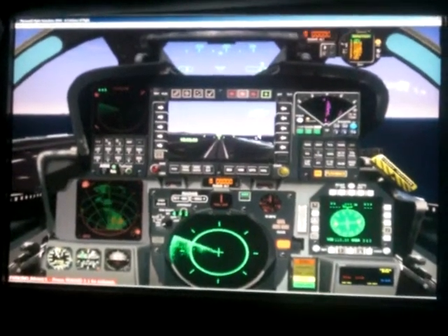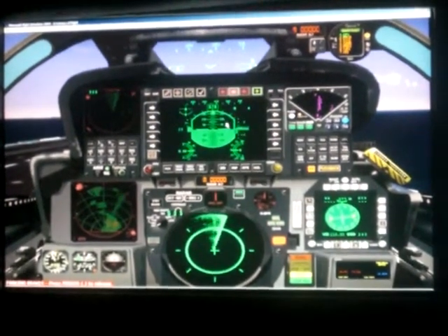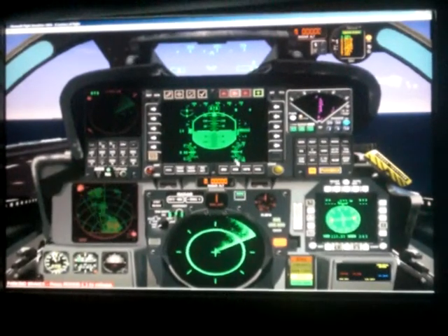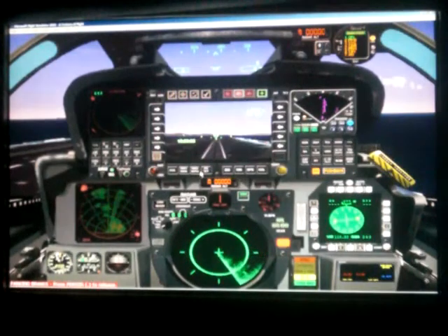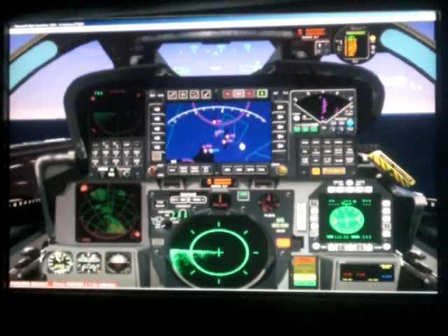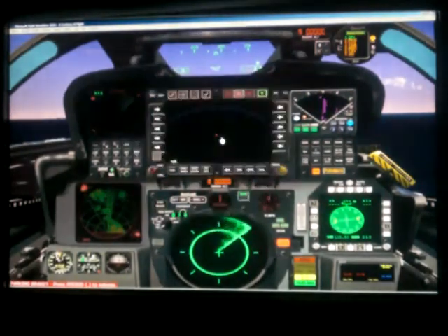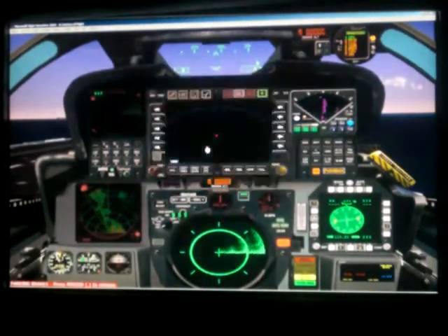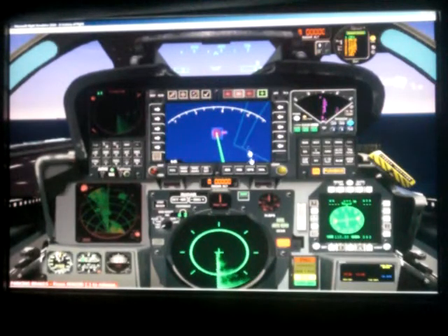The rear seat has a several layer deep multifunction display. It starts with an ADI attitude ball and VSI that you can fly from the rear seat if you want. You can turn that off. You just click these off and on. An HSI, horizontal situation indicator, toggled off and on. The GPS moving map mode, which if you toggle the screen will actually turn it into terrain, and then you can use your GPS zoom to zoom down in on your current location. And then again, to toggle it to the other view, you just click the screen.